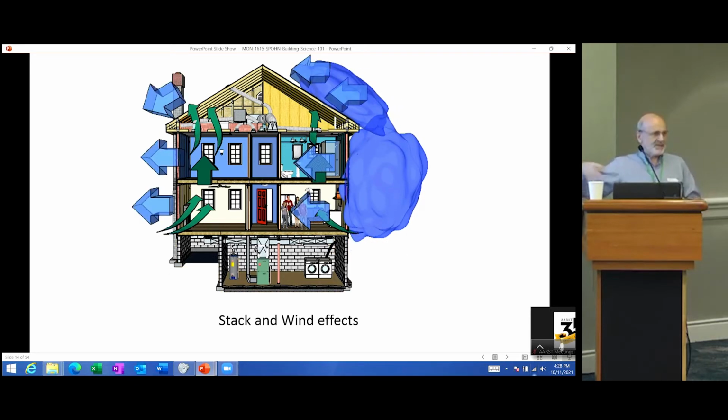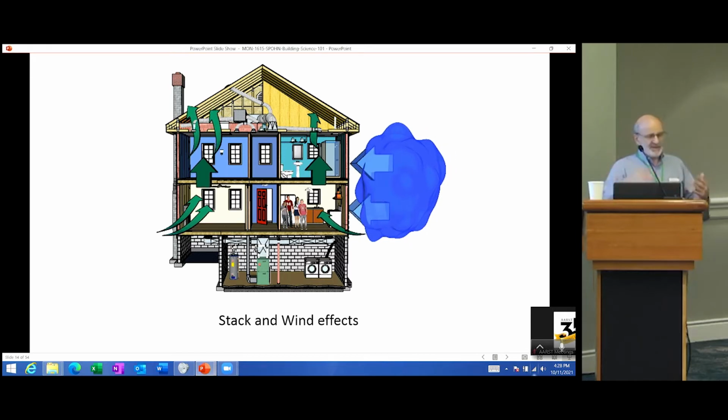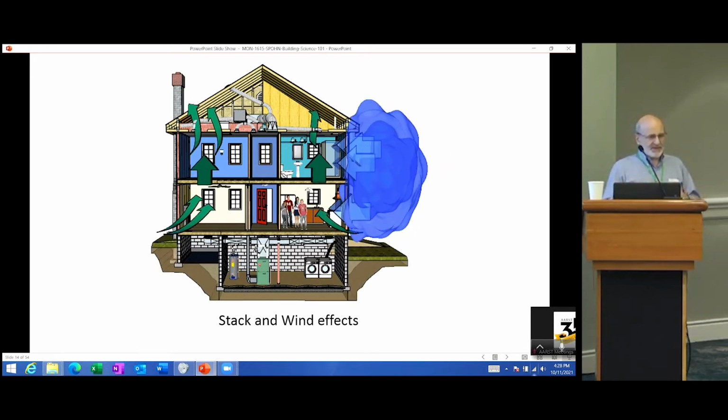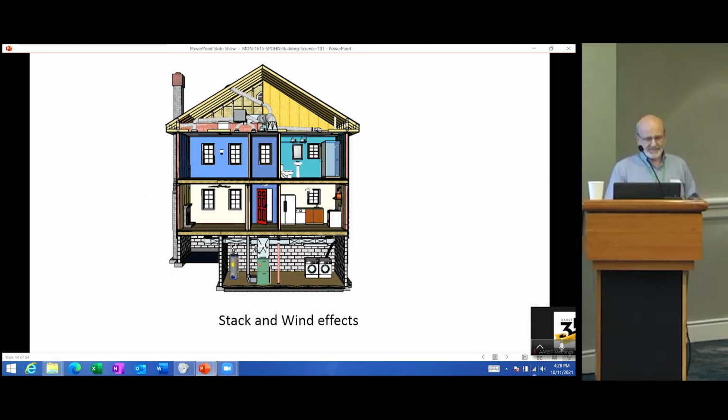And one of the things in building science is called combustion air zone measurement. In as much as a lot of people here measure sub-slab pressures to understand what's going on in the pressure drive there, you can also have these pressure differentials created by the wind and stack effect and mechanical ventilation upset the operation of equipment and cause other indoor air quality issues.